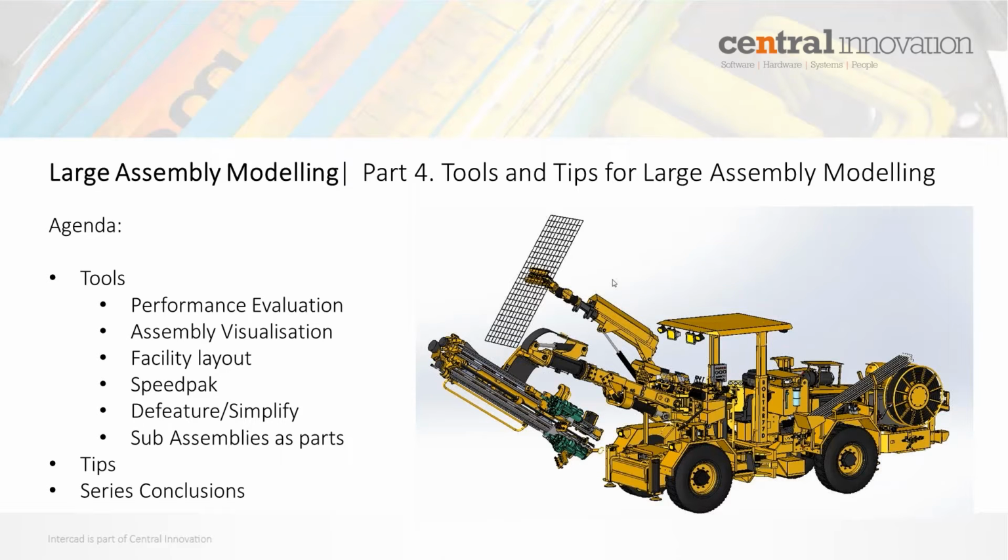The agenda for today, just wait till everyone can see that. So first up, we're going to have a look at some tools. The first of those is the performance evaluation tool. It's a quick tool just to help you narrow down some potential issues that you might see in SolidWorks. From there, we'll move into the assembly visualization tool. This is a little bit more powerful, and it's for interrogating SolidWorks in a little bit more depth.